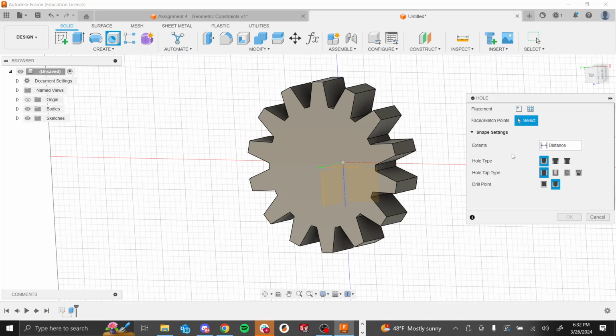at which you want to drill a hole, right? Something that you could do is create a sketch and then put in a bunch of points on that sketch, and then use the hole tool and select all those points on the sketch to create holes. But in our case, we're just putting it in the center, and we drew everything at the origin, so it should be pretty straightforward.